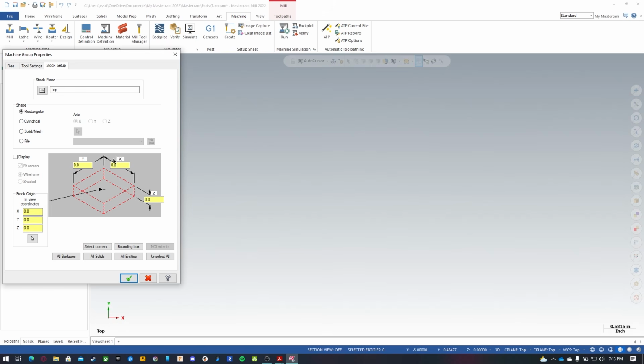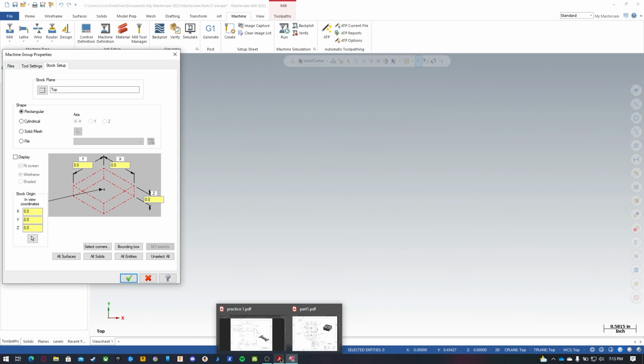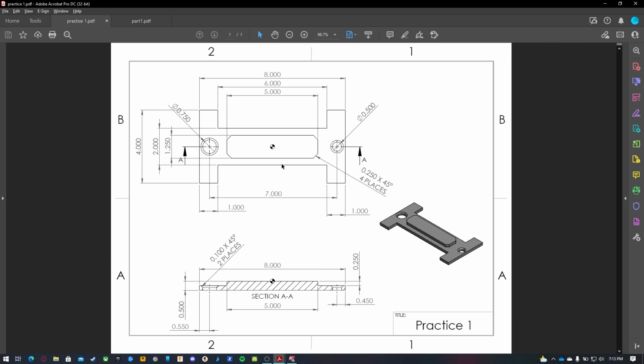Now I want to find out what material that I can get off the shelf or from the store or the mill that will allow me to produce this geometry. Generally, it's going to be oversized by a little bit. So let's say that we have a 4-inch height and an 8-inch width. Okay, down here we also have a 1/2-inch thickness.